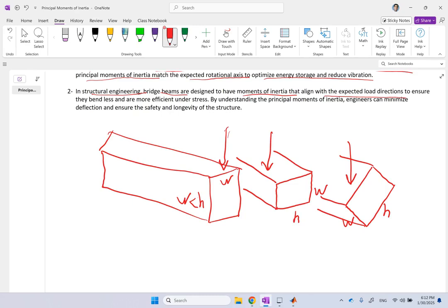And you'll find that in this case, this first one is the best one to do for the orientation of the beam. Because what matters in this beam is I about this axis, perpendicular to the load, and you want to maximize the I about this axis, which is the axis of bending. So you want to have the maximum. Now, in the case of a rectangle, that's so easy. The principal axes are already the ones that are passing through the axis of symmetry like this. And between these two, this one here is bigger.